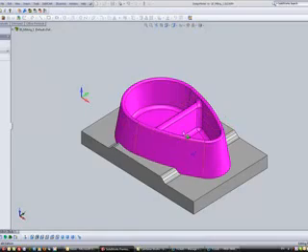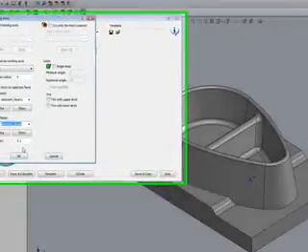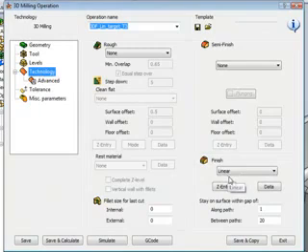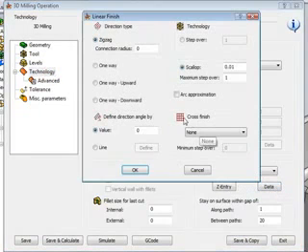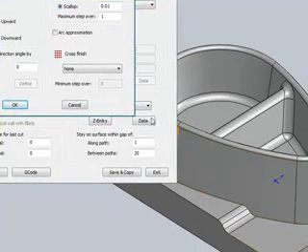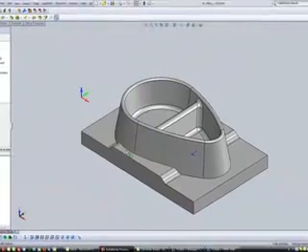This area around here, also staying 0.1 millimeters away. In the technology area, we'll be using linear, and in my data area, we'll have a scallop of 0.01 to give a really nice, smooth finish on the part itself.